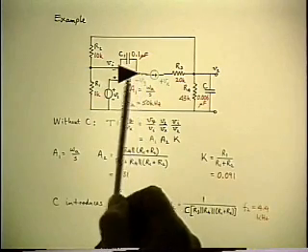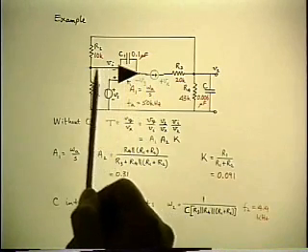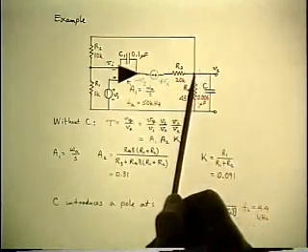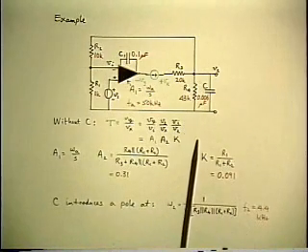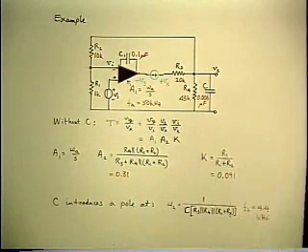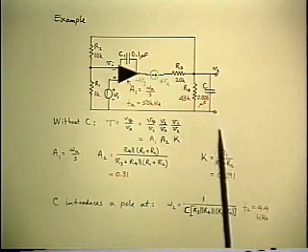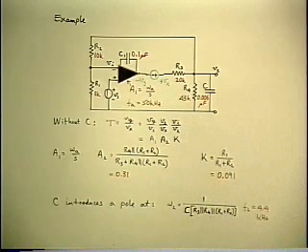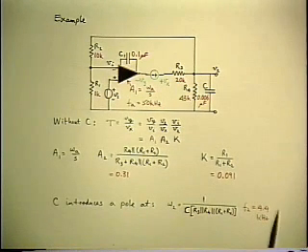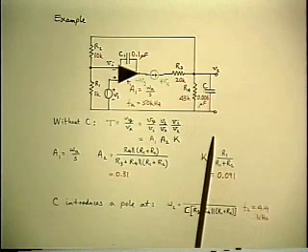If Vy is null, Vi is null, which means V2 is null. But that's right across the second source. So regardless of what current the second source drives in, zero voltage is developed across it, and Rn is 0. So there is no zero in the response.